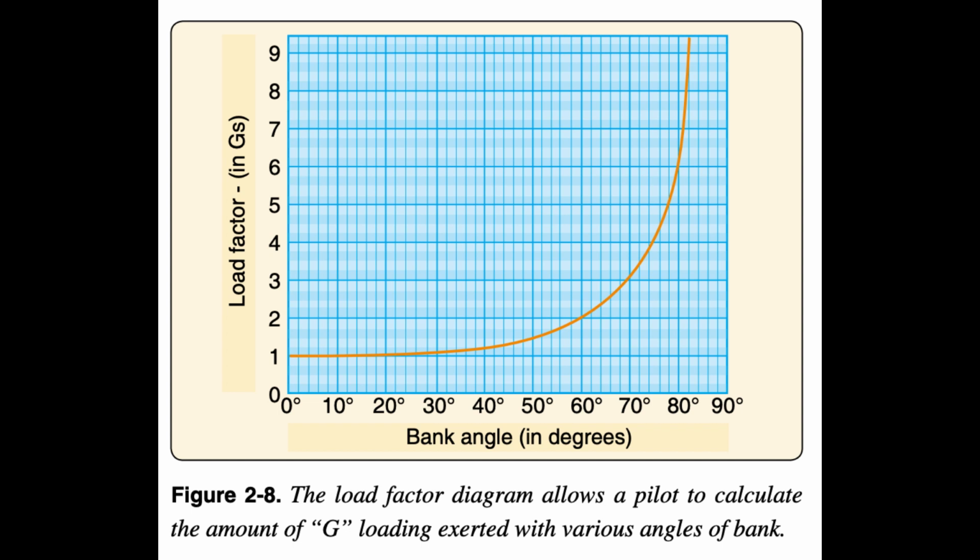The tighter the curved flight path is, the steeper the bank is, the more rapid the flare or pullout from a dive is, the greater the load supported by the rotor. Therefore, the greater the load factor must be. Figure 2.8.